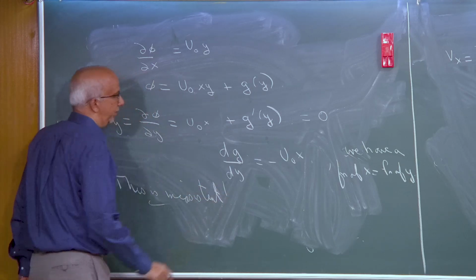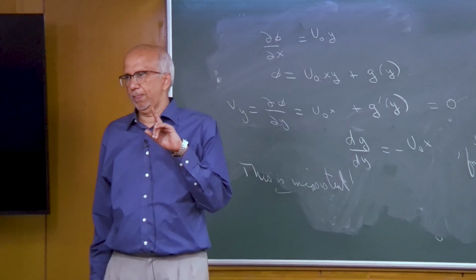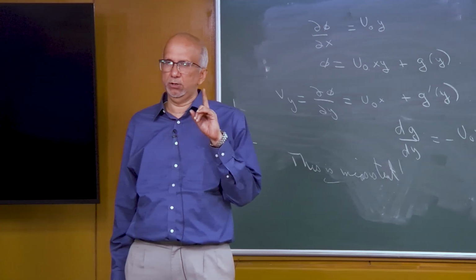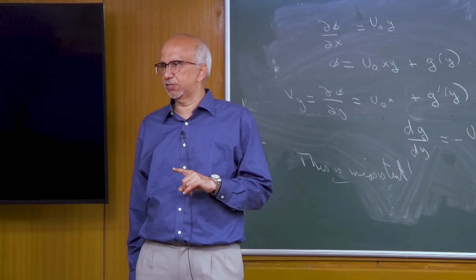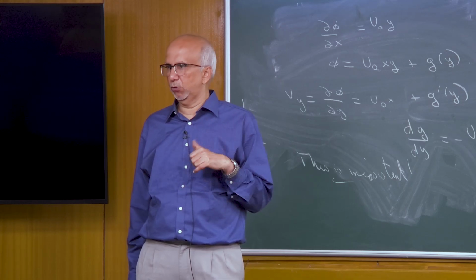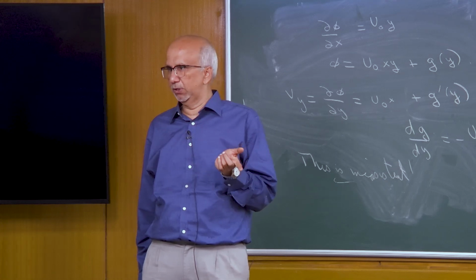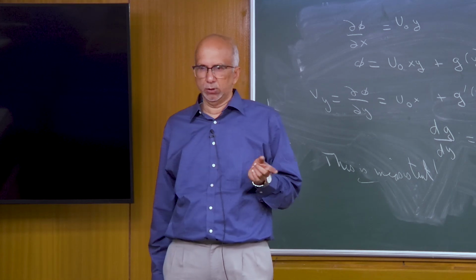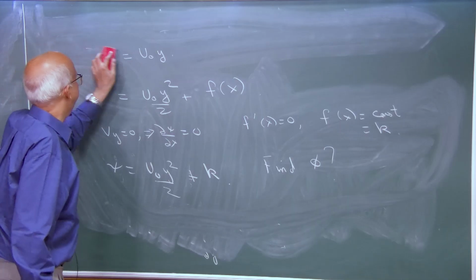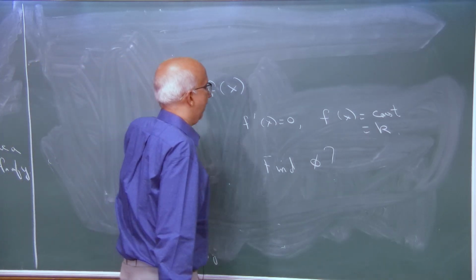So, there is a problem here, and what is the problem? The problem is my flow will have a potential function only if it is irrotational. Okay. I need to check if my flow field is irrotational, which means omega, the curl of V, has to be 0. Okay. So, I want you to check that. Because only if my flow field is irrotational will I have a potential.